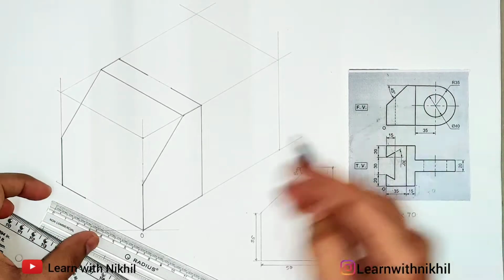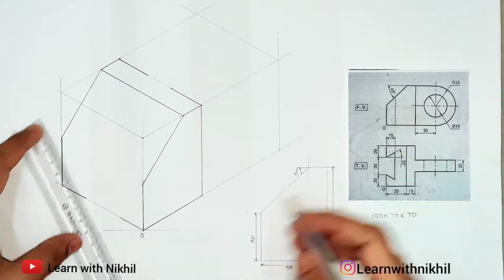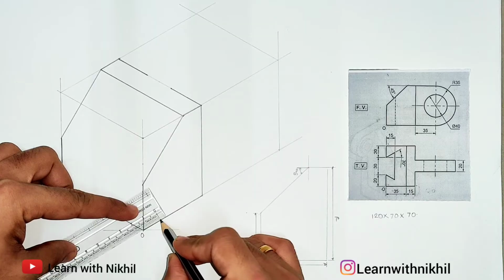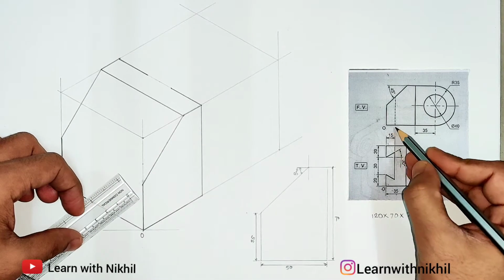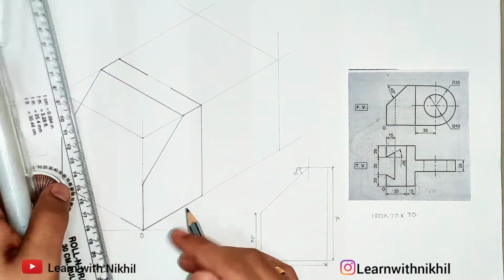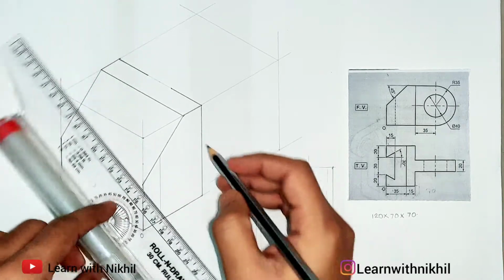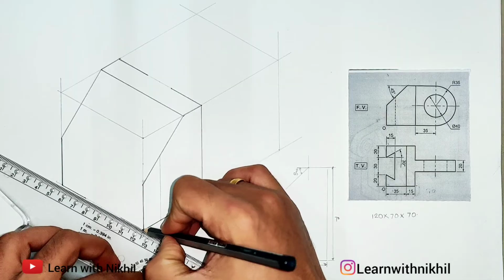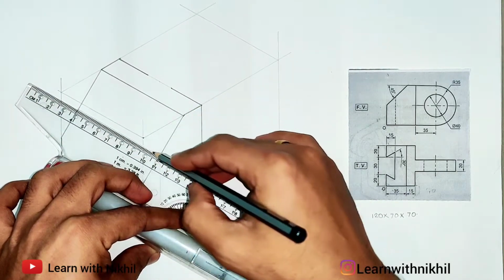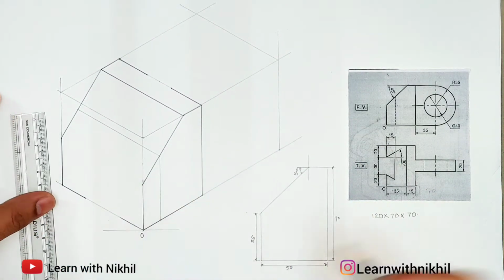Now this is how it is cut from top to bottom. It is cut on the slant part as well. So it's a bit tricky to draw. Now first it is cut at a distance of 15 millimeter. As you can see, this part is 15 millimeter. The depth of the cut part is 15 millimeter. So from here I'll project the light line upward, taking this as the parallel reference line. I'll project this line here. So this is how we have drawn the depth of the cut part.